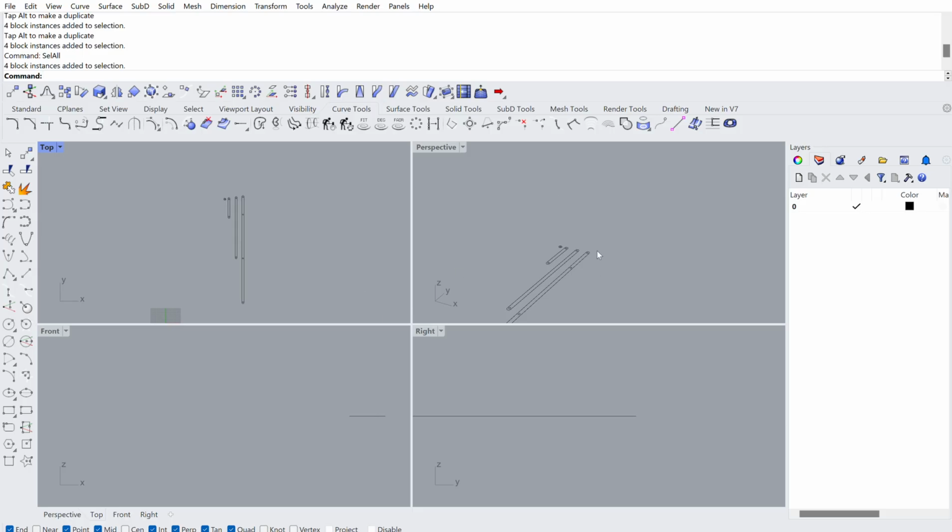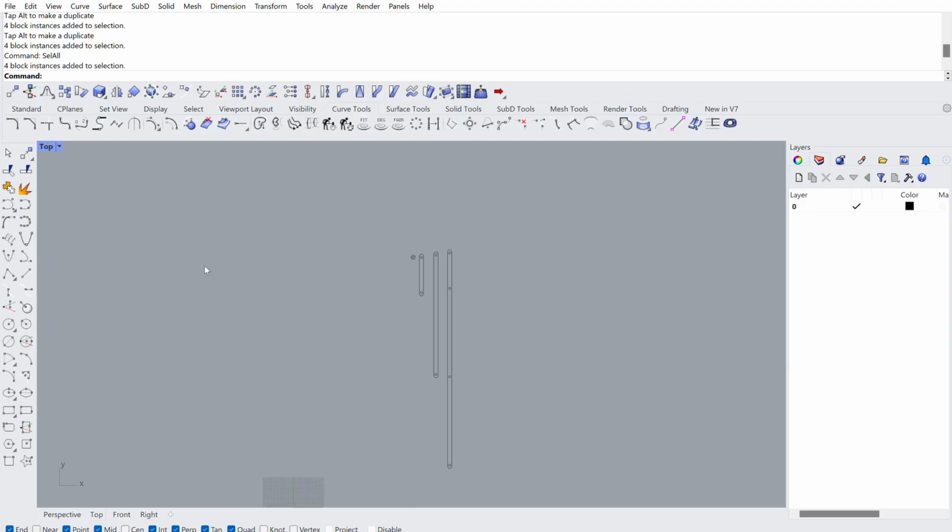So here we have the 4-panel view. Rhino, again, is a 3D program, so you have perspective, right, front, top. You click into any of these, it will show that. You can also go between them. When you are in some of these, like top, front, or right, it will constrain sketches to be in plane, versus when you're in perspective, if you were to be sketching, it may be kind of anywhere in space, because it's not constrained to be planar. There are ways also to control that or make planes, etc.